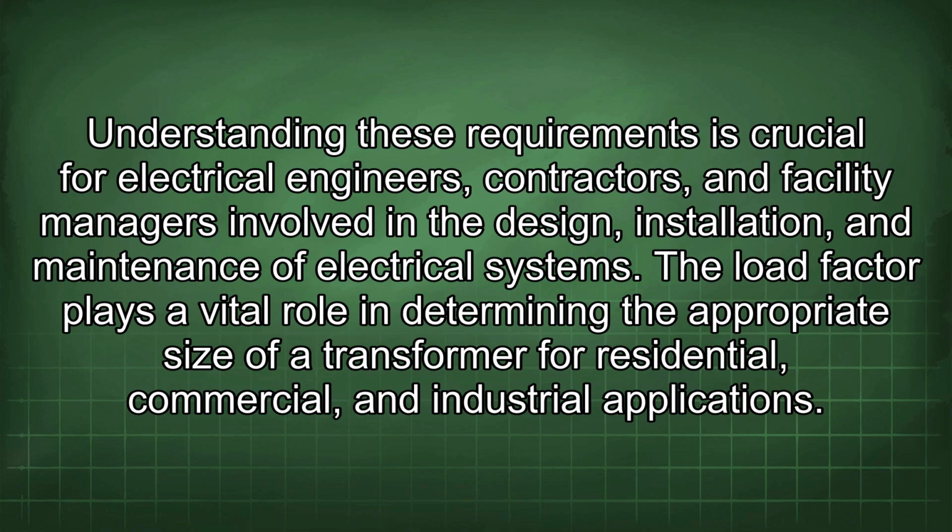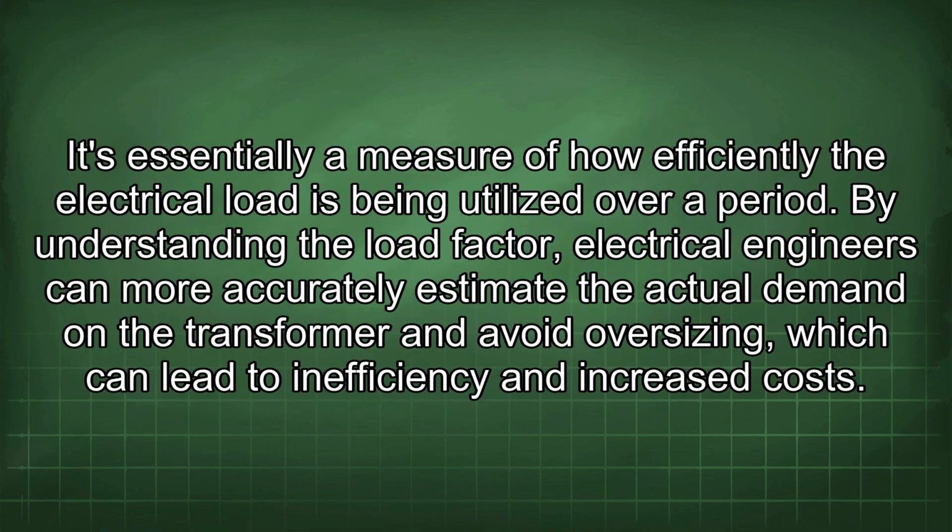of electrical systems. The load factor plays a vital role in determining the appropriate size of a transformer for residential, commercial, and industrial applications. It's essentially a measure of how efficiently the electrical load is being utilized over a period. By understanding the load factor, electrical engineers can more accurately estimate the actual demand on the transformer and avoid oversizing, which can lead to inefficiency and increased costs.